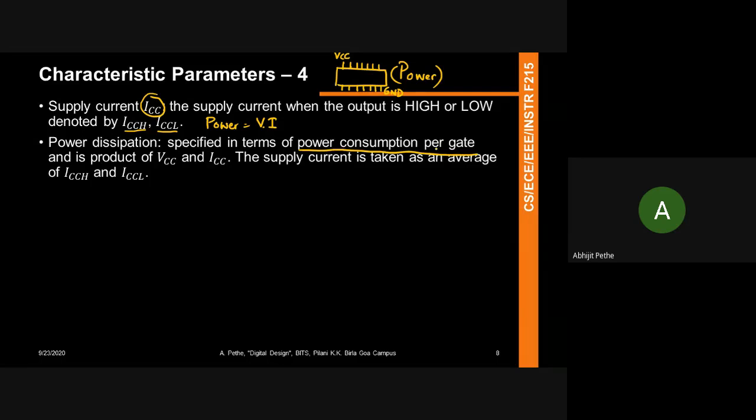Many times when you're designing a system, say a handheld system, you would have a power envelope. Your customer would say, at no point should the power consumed be more than, say, for chips on the iPhone, requirements such as 1 microwatt or 100 nanowatts, which means the power consumed in that module should never exceed 1 microwatt. That gives you the power envelope. You normally design such that you meet the speed requirements while keeping the power below the power envelope that has been given to you. And that's the common design technique.